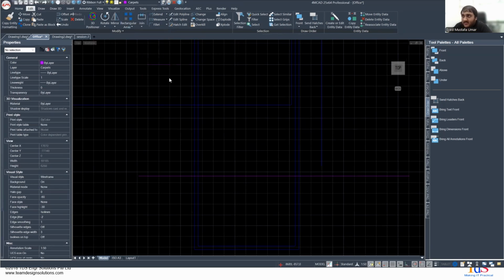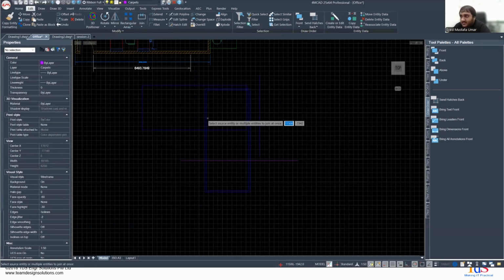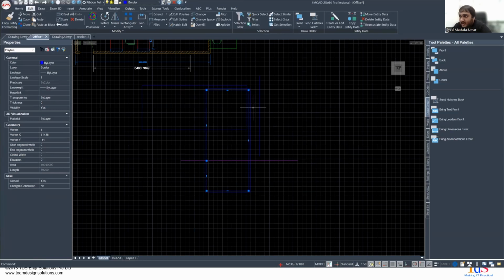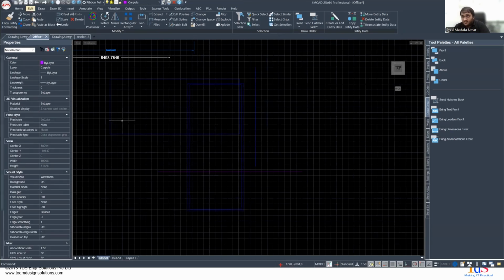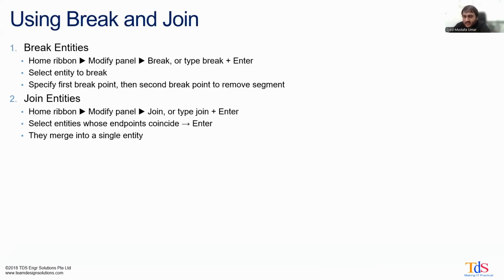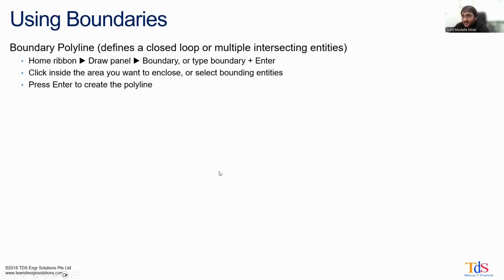And all that join does is basically they're essentially the opposite, where I can select different entities. Let's select all these lines that we broke up right now, and we see that now it's an entire object back again. It was a polyline previously. As we see these other ones, they were polylines, and now this one's a polyline as well. So that's how break and join kind of work. Break at point is what I prefer, so I would advise you on using that command as well.